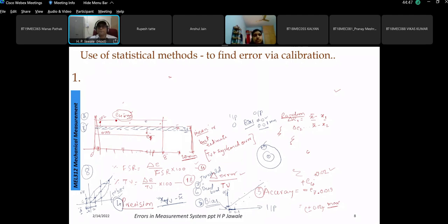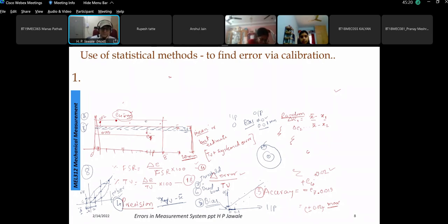Then we have gone through the measurement of the linearity. So linearity is nothing but the deviation between the actual performance curve and the ideal performance curve that is required from the measurement system. And then we express that in terms of percentage over the full scale, right? Then we also found the hysteresis in the input values, hysteresis in the output values, and the percentage hysteresis present, right? So with this, I think we have seen most of the static properties into consideration.